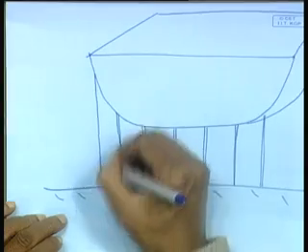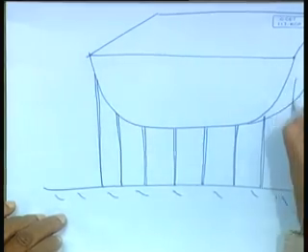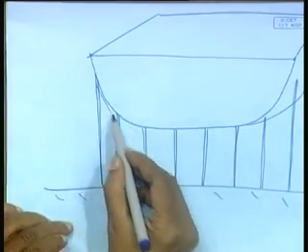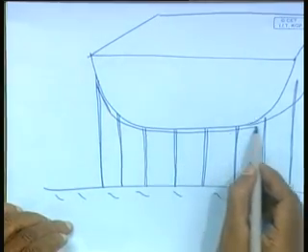This frame structure has a twofold purpose. It has vertical members, and also along some of the frames. Basically, it is a kind of fixture over which you put the curved plates. So, it supports the plate over which you will weld everything, say if it is a double bottom, the stiffeners you will weld, you put the floors, all that you will be doing, as well as it checks the plate you have curved, bent, whether it has been bent correctly, because the shapes should match.